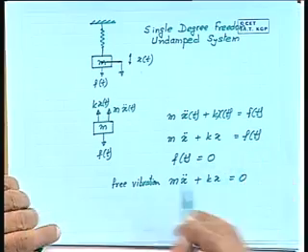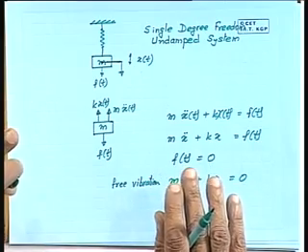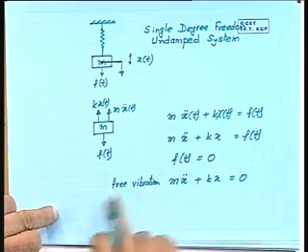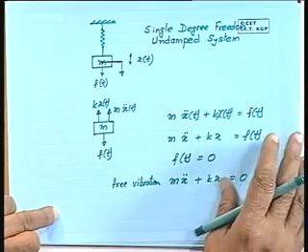When we say a forcing function is being applied, then you keep doing like this. But when I am disturbing it and leaving it, at t is equal to 0, I am disturbing it and then I am leaving it alone. That is a free vibration case. After that, how it behaves. Okay. That is why after writing this expression, I say that f of t is equal to 0. And then I say this is the free vibration governing equation.